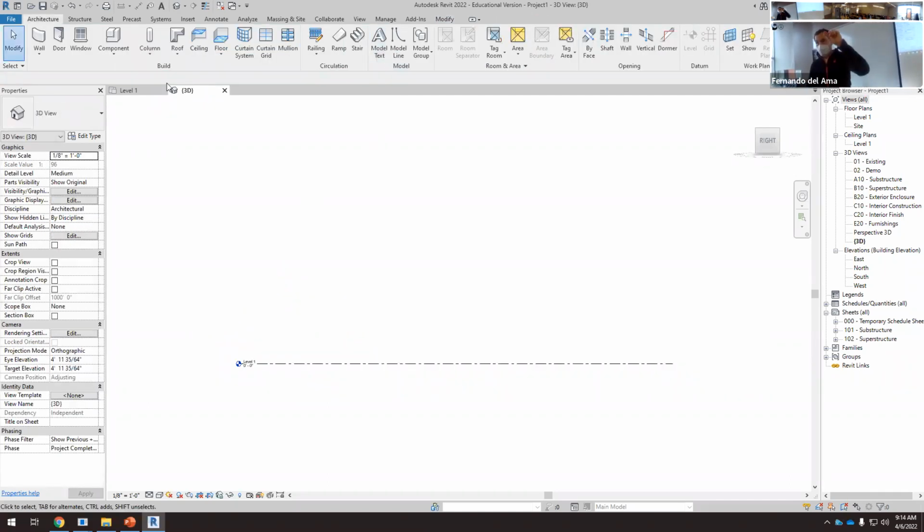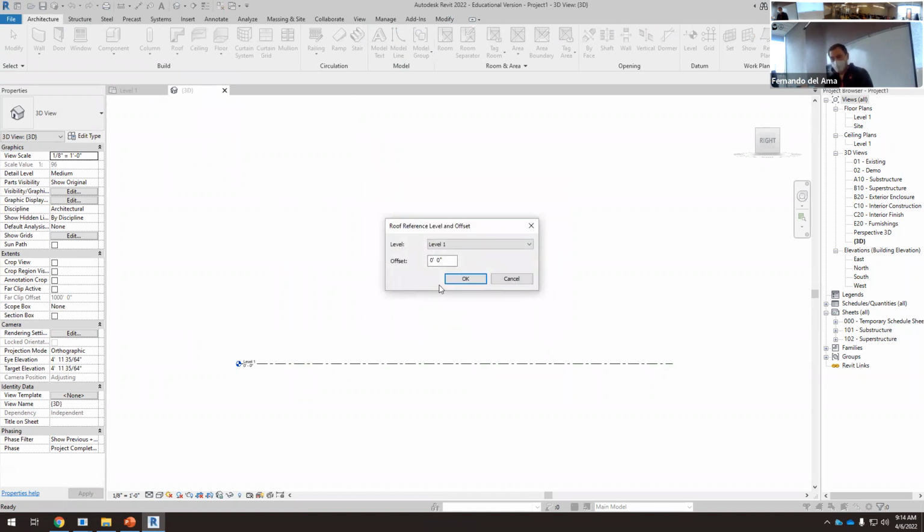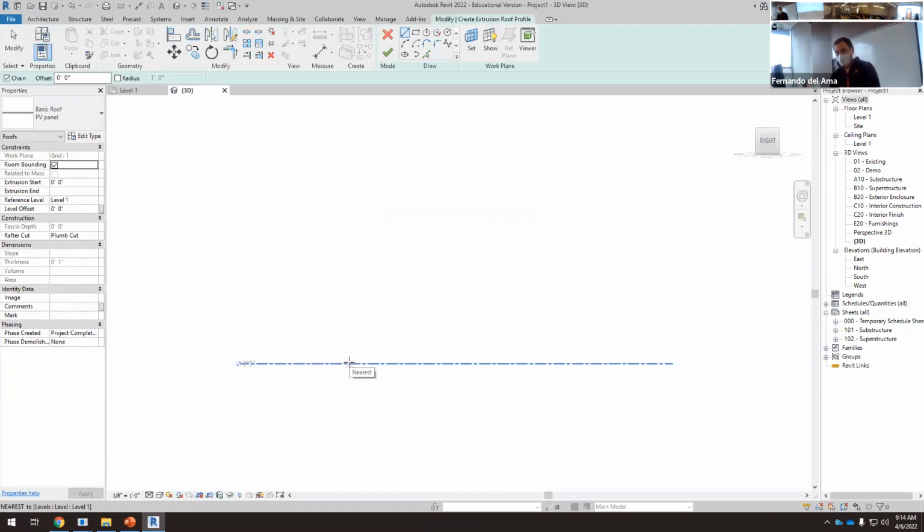I have created a roof with 1 inch, and now I am working with roof by extrusion. I have to pick one of the grids, grid 1, and now I have to work with the angle. If we have to orient this to the south, the angle has to be in this direction so that the south is here. What's that angle? If it's 10 degrees, usually when we are talking about angles, if this is the horizontal and this is the PV panel, if this is the south, for sure we're talking about this angle.